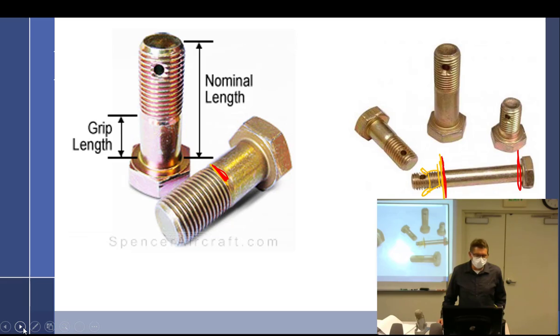So if I'm bolting something together, let's think about bolting your wing to your airplane. You're going to have 2 holes usually that are part of the spar that comes through, and then the wing is going to come through with another component there, and so you have a bolt that goes through 3 holes. Okay, if I have a bolt that is kind of the right size, because these things are going to have a tolerance. They can be as small as this or as big as this, and still call it an AN4. So there's this range that they're made in.